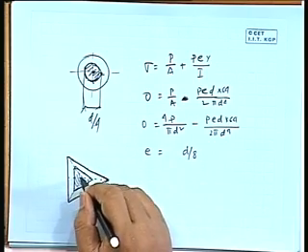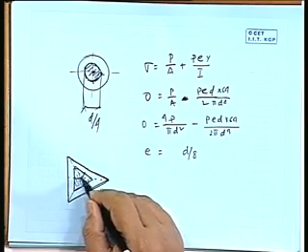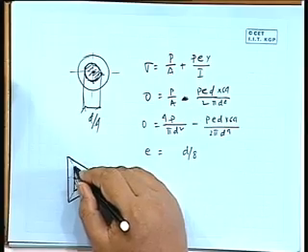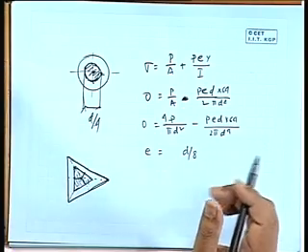So only this distance you have to find out. If it is equilateral, all the sides will be the same amount, right? And you can enclose, that will be the area. So within that, if you apply the load, the section will be under compression entirely. So for that type of section, it will be the core. Sometimes we require that information, how will be the geometry of the core and what will be the extent, right?